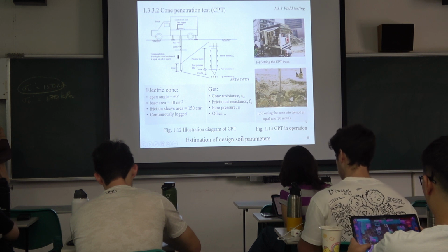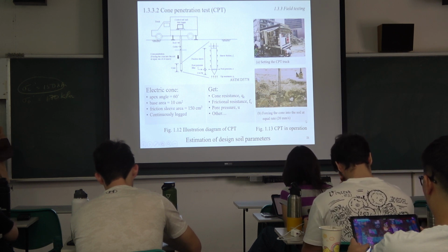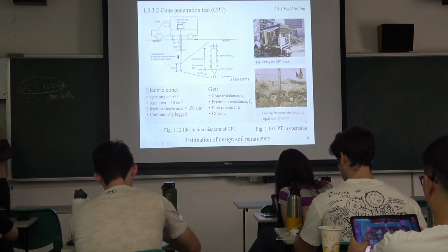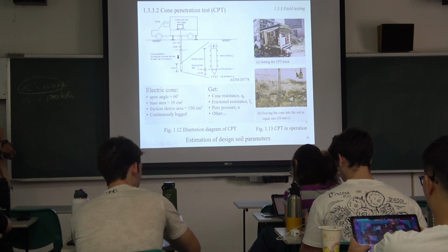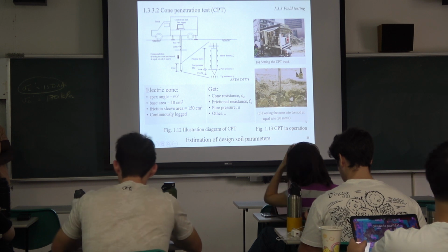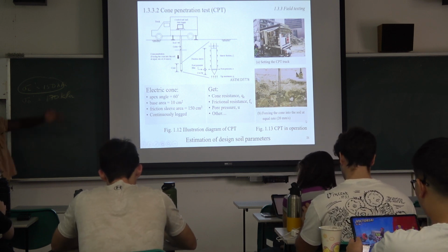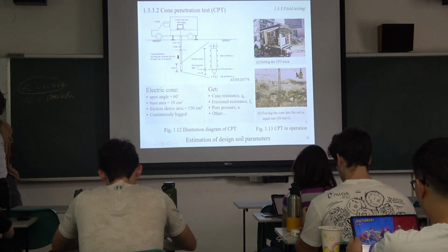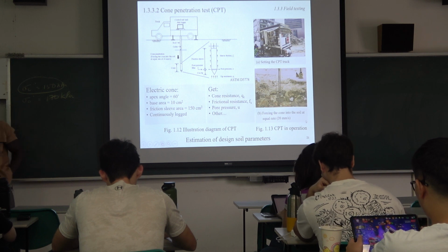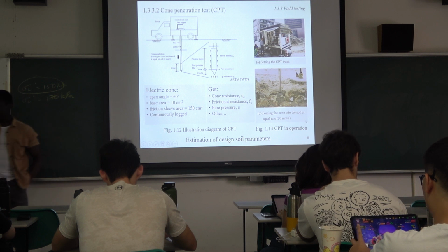I remember in chapter 3 you did a lot of work, like when you calculate the bearing capacity, the settlement, and all that. But for all the problems you did, someone will give you the C, the phi, or the undrained shear strength. But if you're an engineer at the site, you don't just get the parameters out of nowhere. You have to do some field exploration test, right? For example, you will do the SPT or the cone penetration test to try to get the necessary soil parameters.